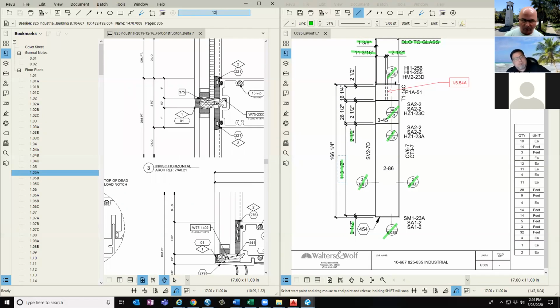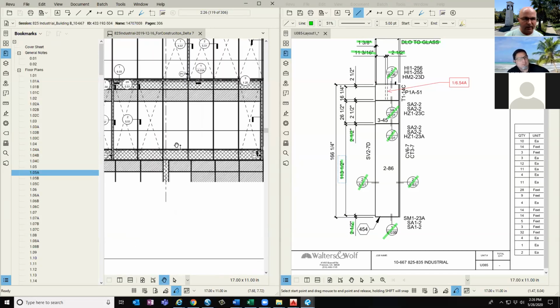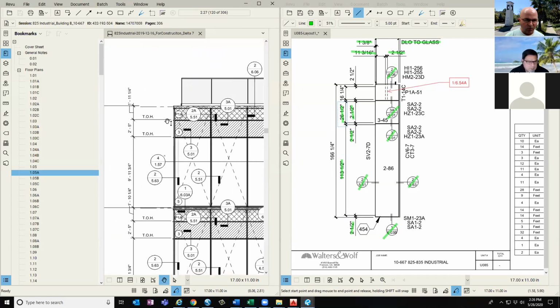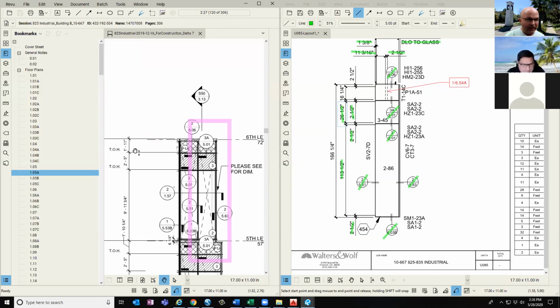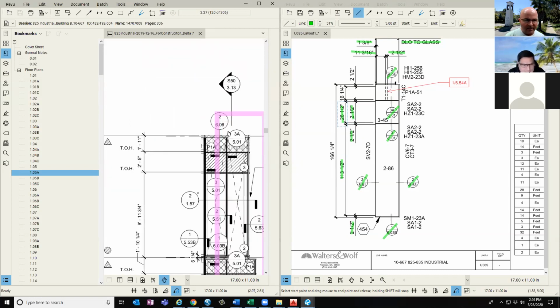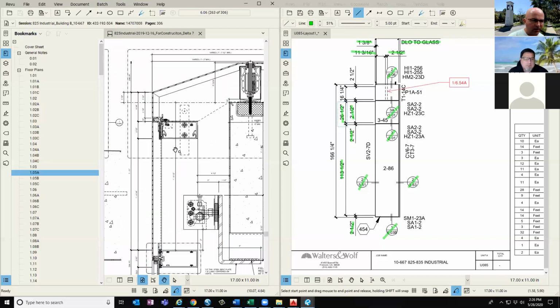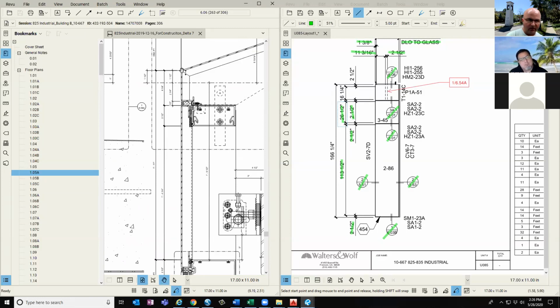In that same fashion, I'm going to go ahead and continue working my way up the unit and getting from this 2'5" top of horizontal to top of horizontal, will equal to my 26.5 daylight. Then when I get to this top detail, I've got a 111.25, and that ties in back into my, it's a 1'11" in this case, and that ties into my 21606 detail. So now when I go to my detail here, I can see my 1'11". My dim point is way up here to the corner of this panel. Then I'll do my deduction to the top of the horizontal and then to the daylight.